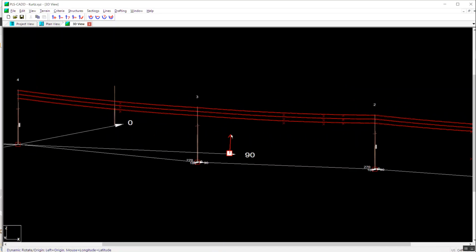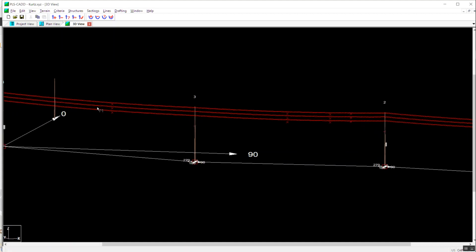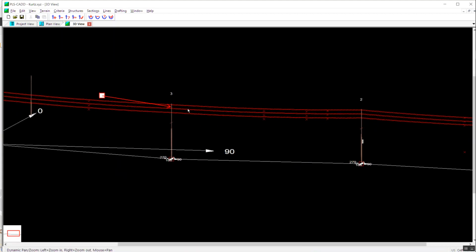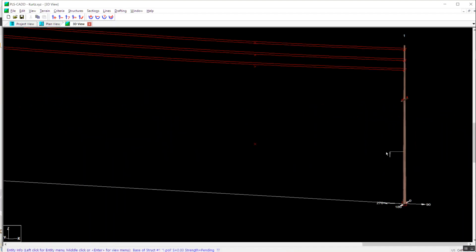And the way it works, you define a location, and then you define a ground point, and then at that ground point you measure heights. So here there were 3 ground points that were defined and 3 heights. And in these other 2 spans, there was 1 ground point with those 3 heights. Here there were 4. There was also a communication wire here that was strung in. That was the height there.